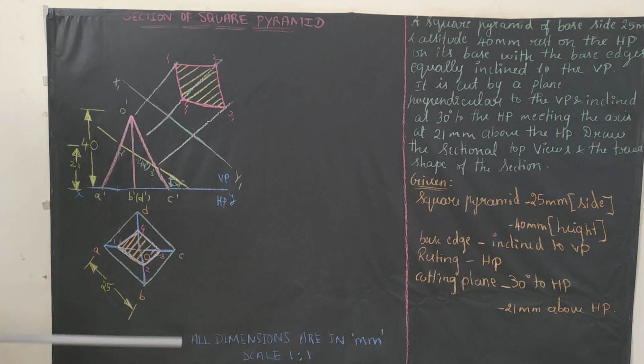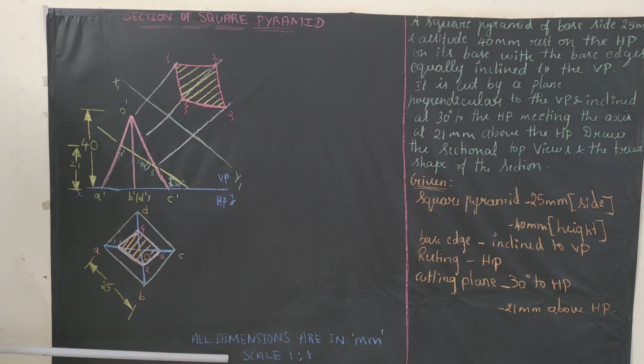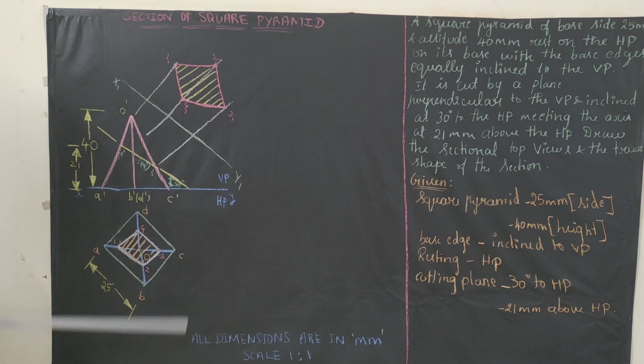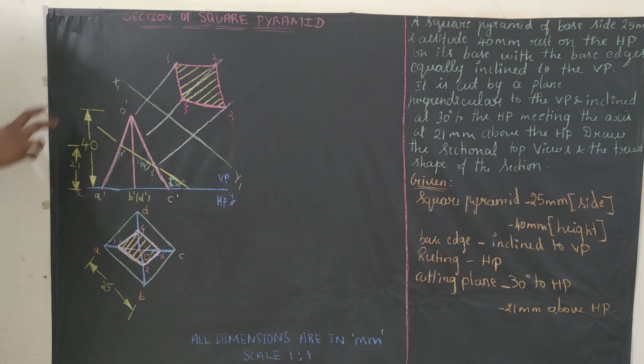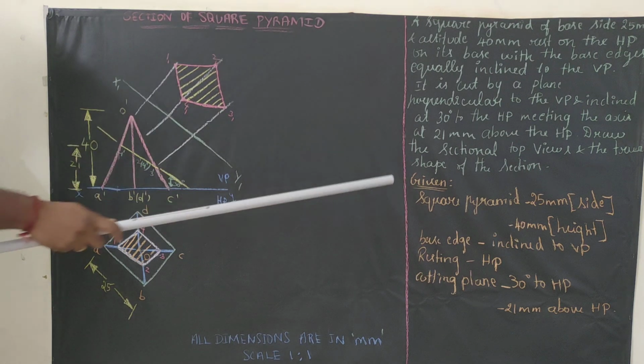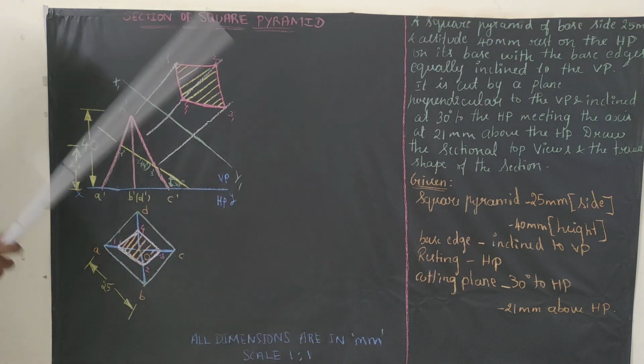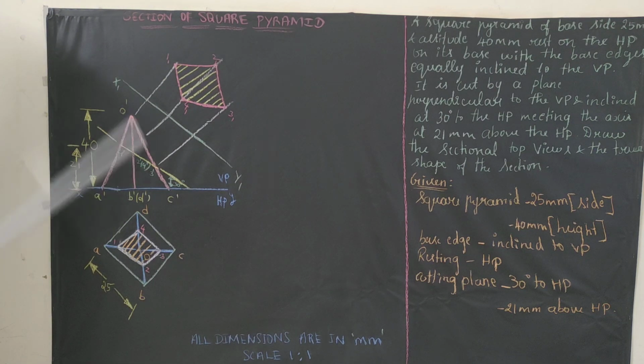Below you will be having 2 lines. All dimensions are in mm and scale 1:1. Height of the text here is 5 mm. Use a pro circle and put the question number. For putting the border from left 20 mm, top 10 mm, right side 10 mm, bottom 10 mm. Try to draw the border for the diagram with your HB pencil. This is the way you need to present your diagram. And if you present your diagram neatly then you can easily get full 20 marks.